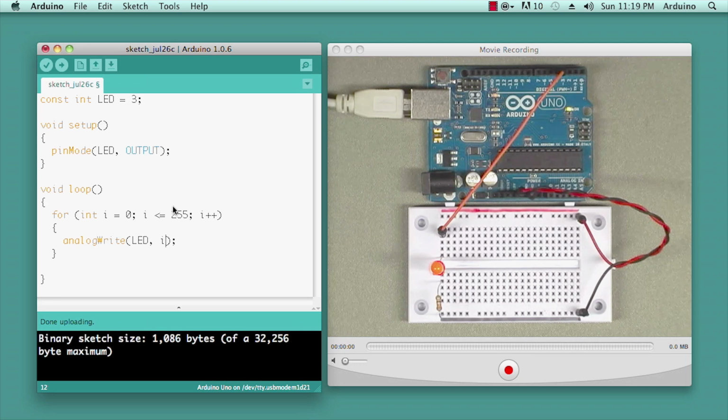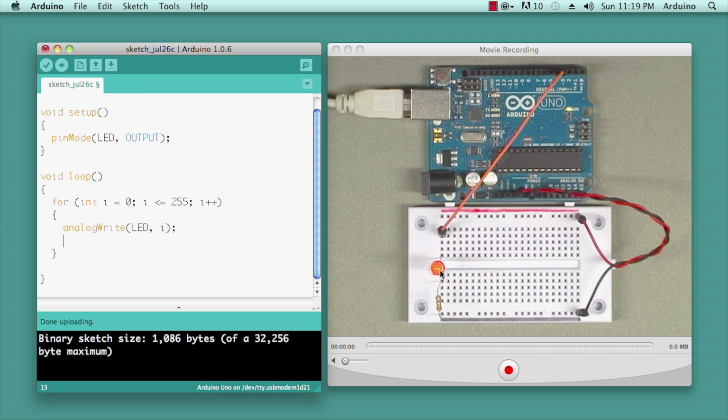But we've broken the first rule again, which is what? Computers are very, very fast. So that's happening so fast that we don't see the result. We have to do a slight delay. And let's do a delay because we're doing a bunch of writes over and over again. Let's start with a delay of 10 and see if that's enough to see the effect.